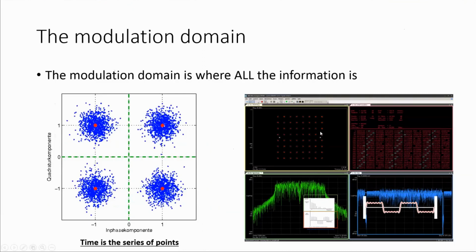And what these states are the I and Q values. And I'm sure most of us have some idea what an I and Q value is, the in-phase and quadrature components of a signal. However, that's an important concept, and we're going to look at it in a little more detail. But if we just consider the in-phase and the quadrature component as axes, or a basis function, we can say, oh, well, there's a combination of values that gives us a state.